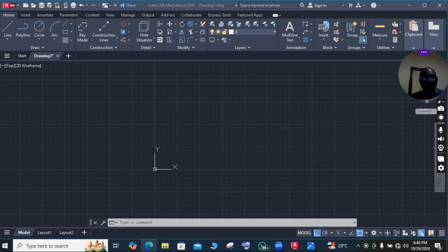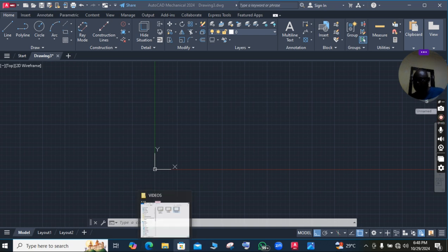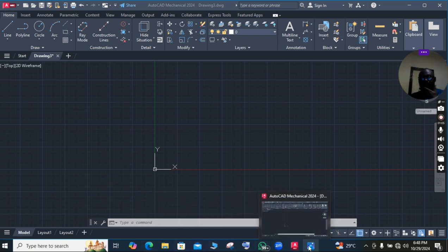Two other ways to extrude are to taper the extrusion and to extrude a shape along a path. You can also combine the two options and extrude along a path while tapering the shape. So in this video we are going to be looking at extruding along a path. The path can be a polyline.